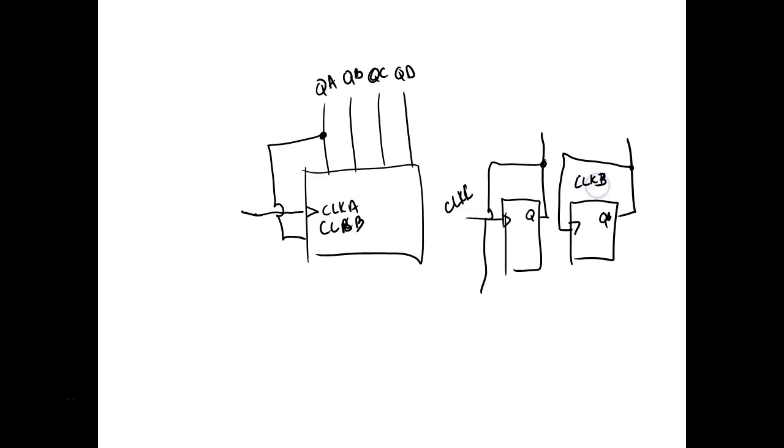So what's going to be clocking B? We're just, y'all see nothing. So with this, we would get the QA output working with the QB. The QB, QC, and QD would not work. The counter would not count. It wouldn't ripple, right? That's a good point.